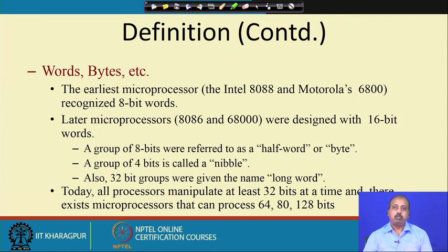Now, when the 8086 was introduced into the market, you could not just take out the 8085 chip and put the 8086 chip there, because the data bus size itself changed from 8-bit to 16-bit. So the hardware becomes incompatible.